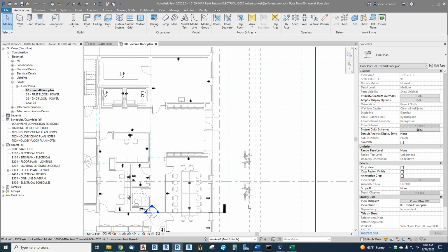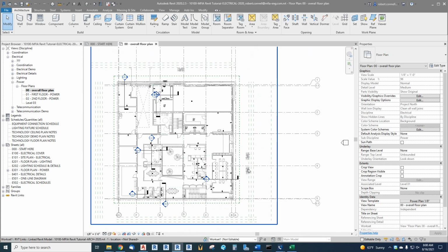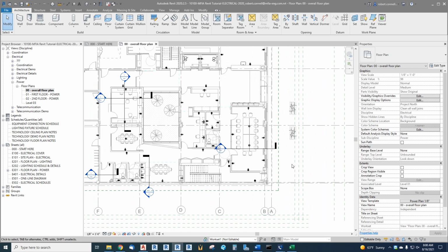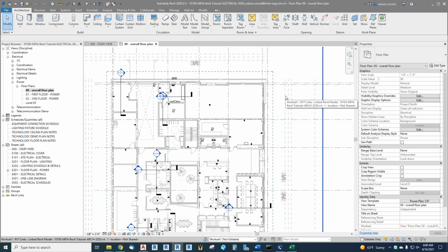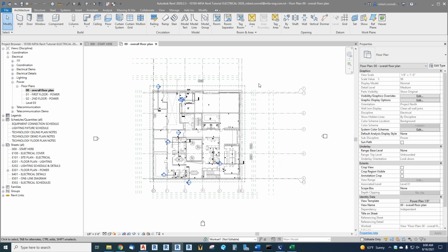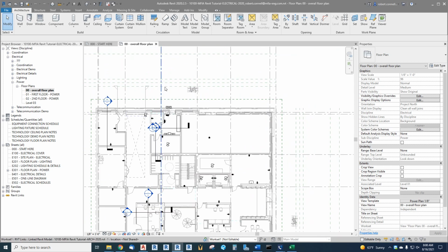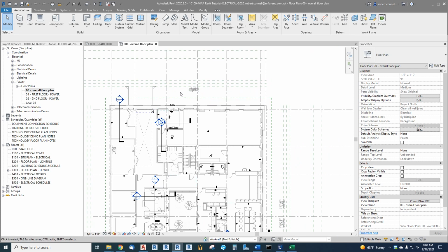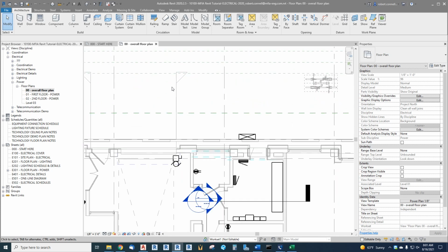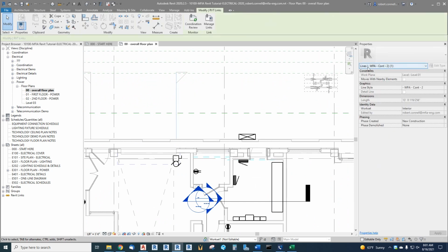And let's see what else. Yeah, that's all we have is bike racks. There's no other site amenities modeled by this architect, which is fairly common. On their site plan, if they even have a site plan, there's probably just detail lines for curbs and sidewalks and trees and such, which doesn't help us because we need model pieces. This here looks like part of a driveway. Let me tab through there. Okay, this is just called lines.